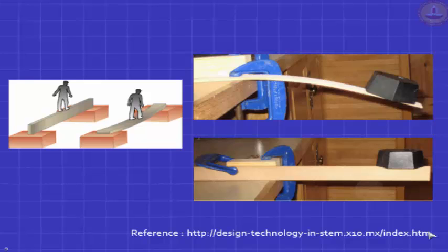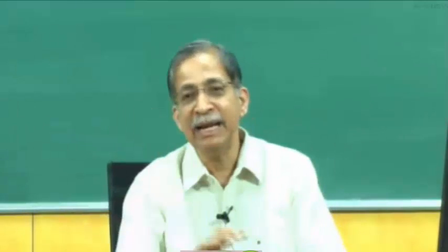So there are two benefits by making a beam bend about its stiffer axis. One, deflections are much less. Secondly, the load bearing capacity is much more, and the ratios can be calculated. Okay, how to calculate deflections we'll cover in the third lecture. We won't do it now.